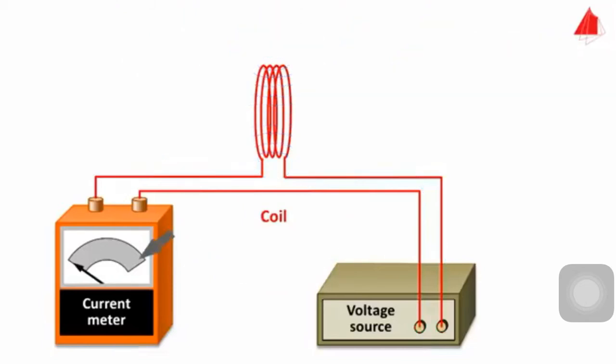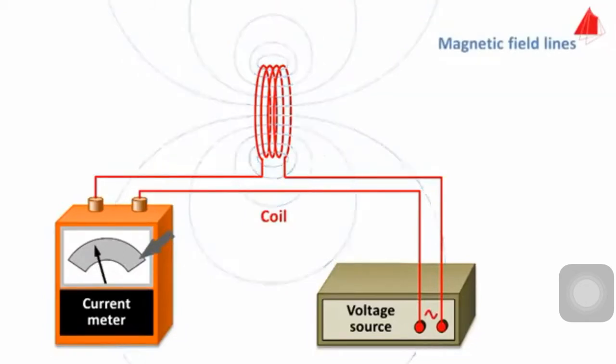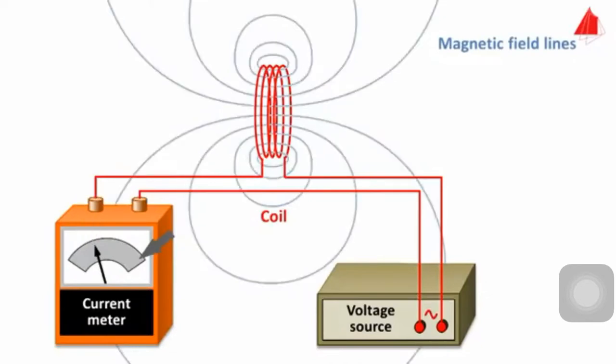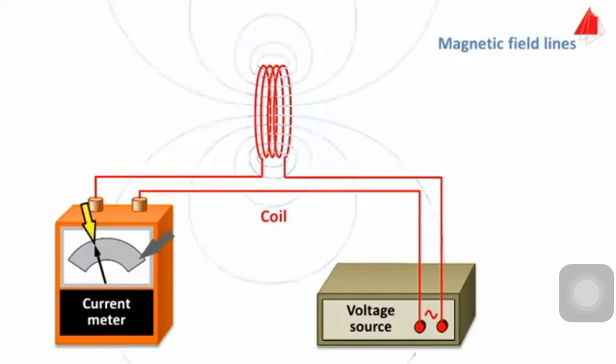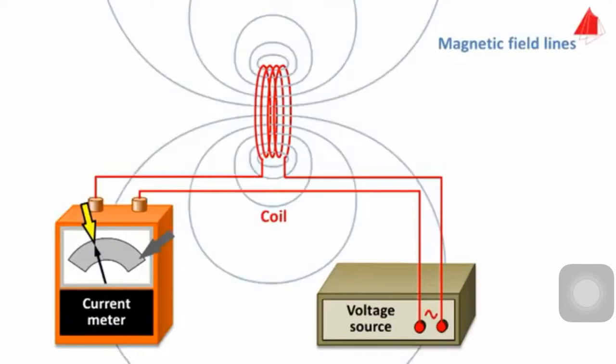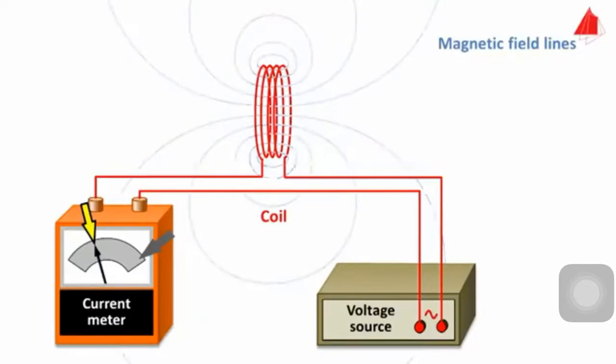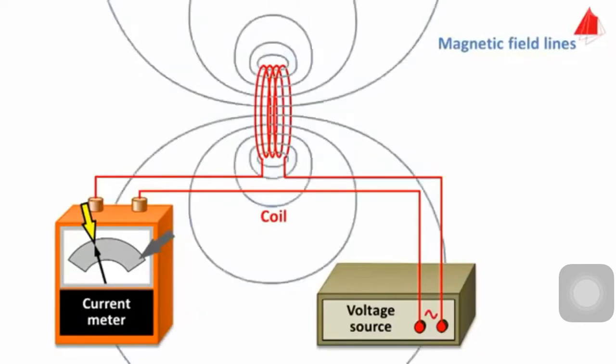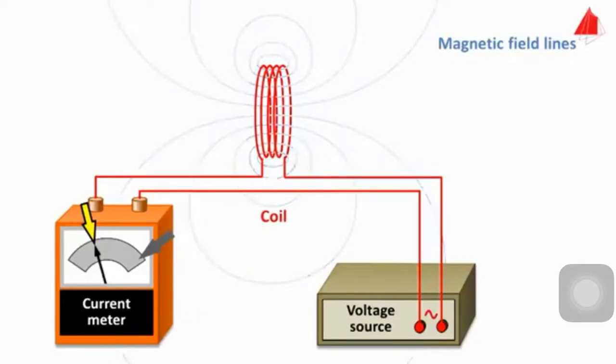If an alternating voltage is applied to the coil, the effective current through the coil is much smaller than when applying direct voltage. The reason for this is the alternating magnetic field, which generates a countervoltage in the coil by self-induction. The countervoltage in turn reduces the current consumption.